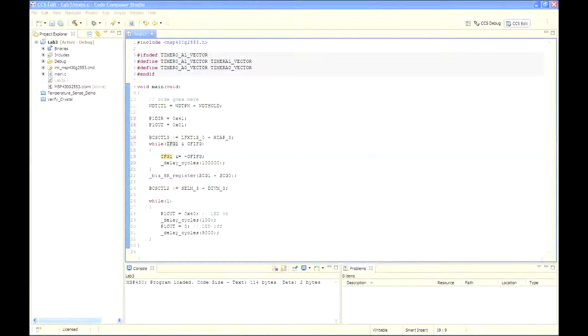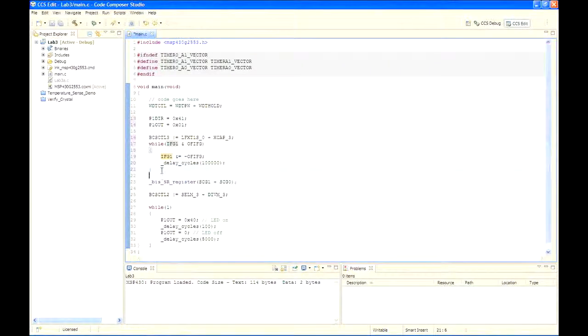In step 19, finally, we need to add a line of code to turn off the red LED, indicating that the fault test has been passed. So add this new line after the while loop: P1OUT equals 0. Since we made a lot of changes to the code and had a chance to make a few errors, check to make sure your code looks like what you see in the workbook and on the video screen. Again, you could have cut and pasted all of this from the file xt.txt, but you're here to learn about each one of these pieces.